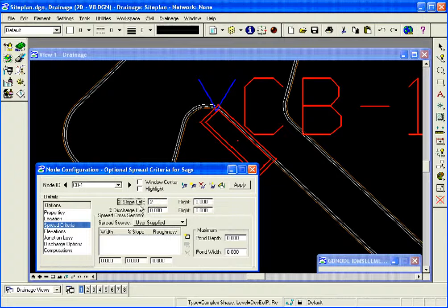In my case, I'm going to say 2% slope from the left, I've got a 0.5% slope from the right, and 10% of my discharge will be coming in from the left hand side and 90% from the right hand side. And these are arbitrary and obviously have to be keyed in, so you as the designer can determine what the percentage of discharge is left and right. I'm going to look at this as if I'm standing in front of the inlet looking and facing towards it.